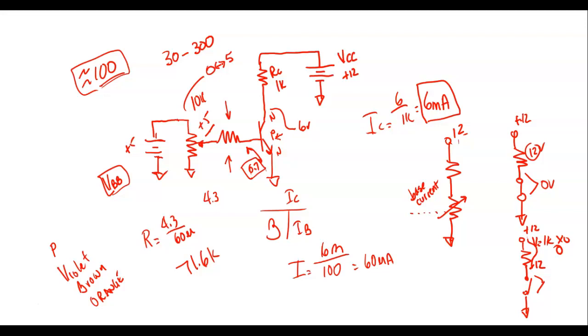So beta is like Ohm's law, right? All you got to know is this first formula: beta is equal to IC over IB. And once you've got a 3-term equation, you don't even have to know algebra anymore. You can just cover up what you want to solve for.